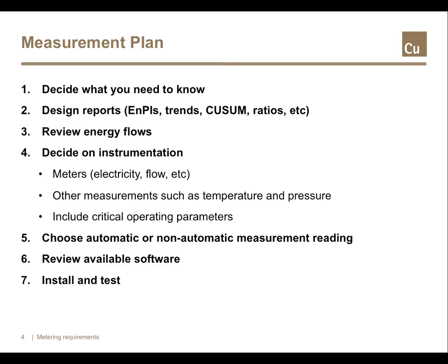Here are suggested steps for a measurement plan. Check first what you want to know before installing meters. Establish who the users will be, what the drivers behind the measurement are, and what are the critical parameters. Then draw up a measurement plan. Design reports, energy performance indicators, trends, cumulative sum, ratios and so on.